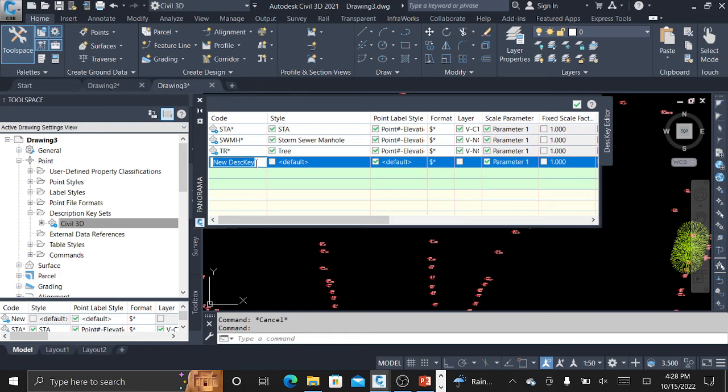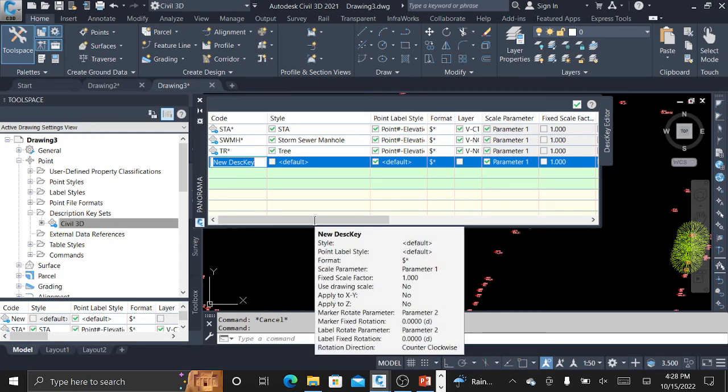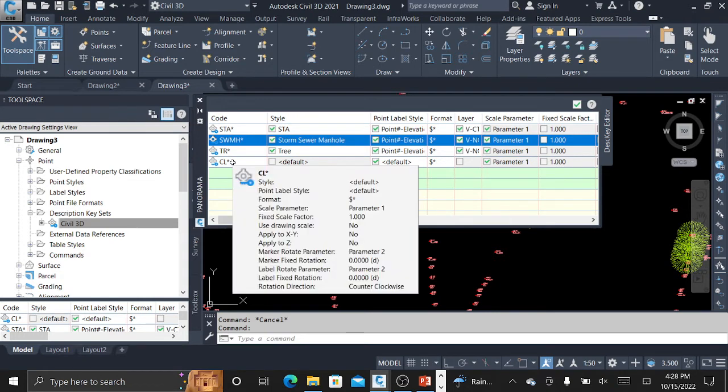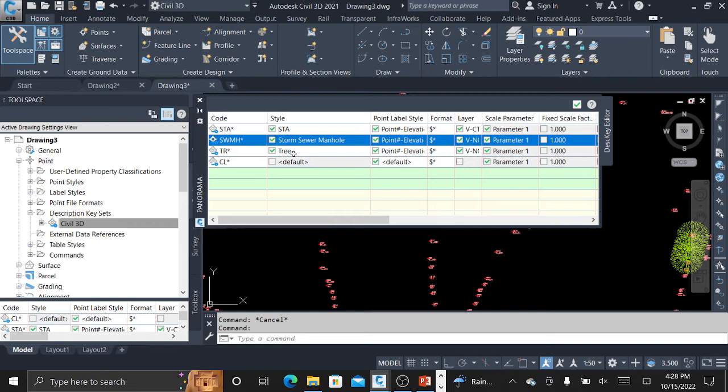All our center line codes, like you saw in our text file, were all called CL, right? So I'm going to type in CL, and I'm going to add a star. That means every point that has CL as a point description, I can apply these other two changes. I'm going to display them differently, okay?